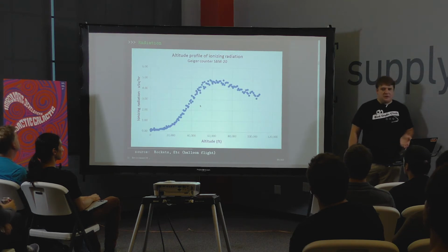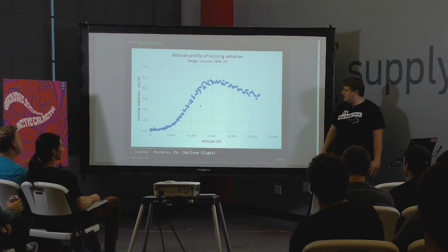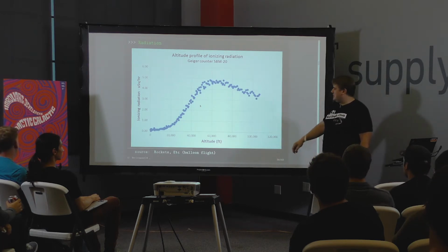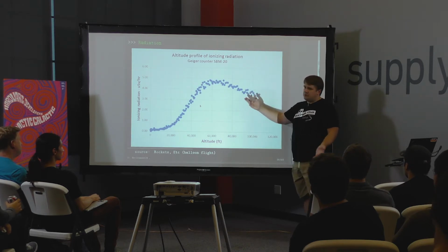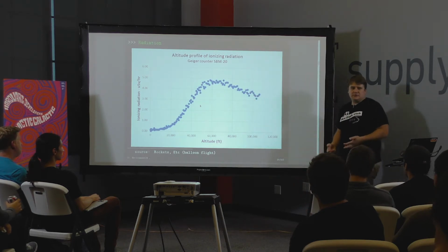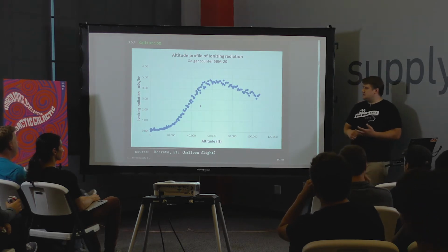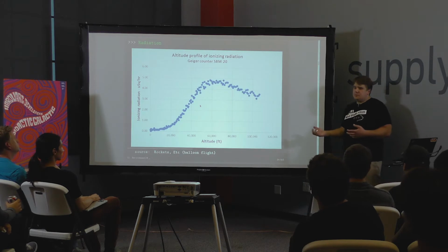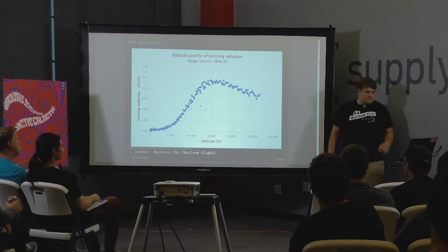And then there's radiation. People fly Geiger counters on balloons all the time. This is measuring gamma radiation, and you can see from sea level up to 100K, it goes up a little bit, but UV goes up, other radiation goes up too. What that means is it'll impact your electronics, but also any plastics you have, because basically something that can last 100 days on the ground might last much less in the sky just because of breakdown due to UV and other atmospheric effects.